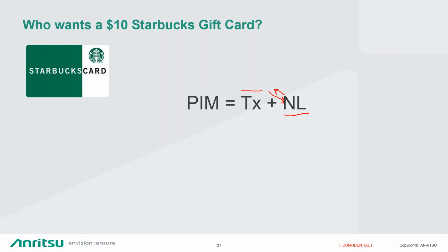Okay. Does your IQ Fiber Master support eCPRI for 5G or greater? So we are watching eCPRI. If you're familiar with the specification, there's different options within eCPRI. We are fully planning to support the option that's carrying IQ data. There are options within eCPRI that do not carry IQ data.